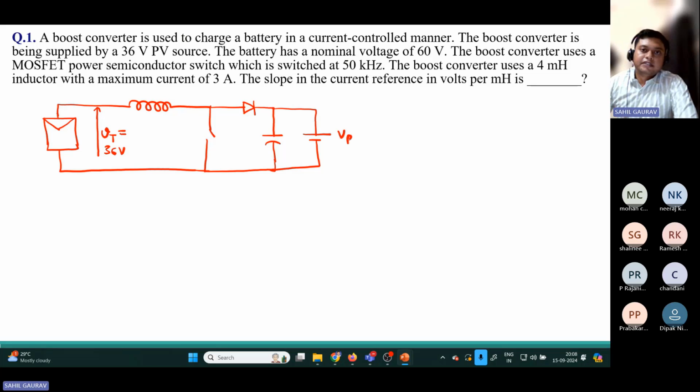And this battery nominal voltage is 60. The boost converter MOSFET is switched at 50 kilohertz, so we are providing it 50 kilohertz, and this inductor value is 4 millihenry, and this inductor maximum value is 3 ampere. The slope of the current difference in volts per millihenry is...